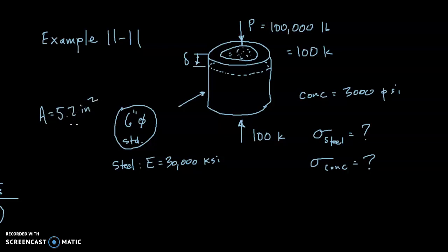And the inside diameter is equal to 6.07 inches. So pipe is nominally designated by its inside diameter. Our pipe is a 6-inch diameter, but you can see it's not exactly 6 inches.